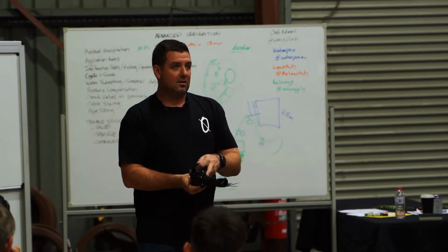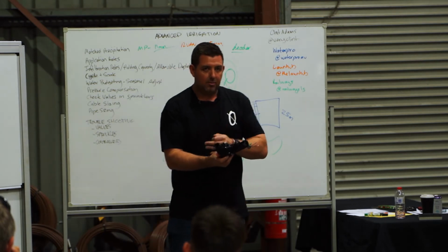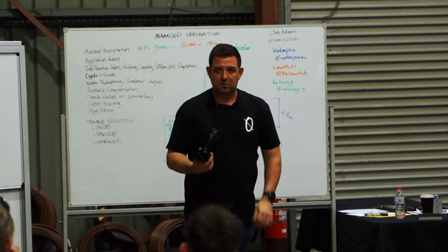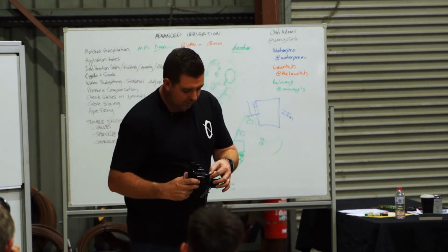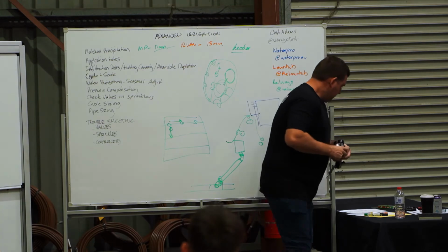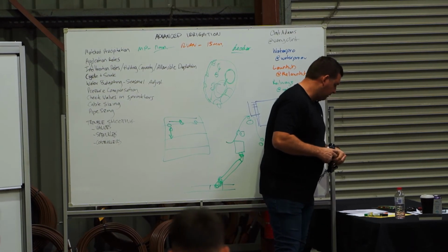The bleed screw does exactly what it's designed to do. It will bleed the top of the valve. That will help clean out any debris that might be above the valve. So that could be something that you could do as a test when you're trying to work out what's going on. What else is there? Valve won't close. That's pretty much it.